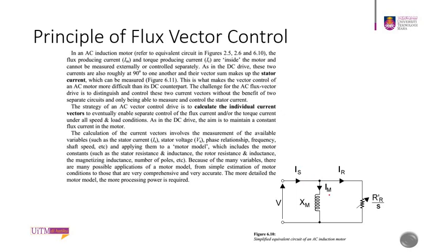Okay, and you can see here from the stator part of the motor, you can measure the voltage and the current input to it. And the rotor part, that is the rotor current, EMF, MMF, you cannot measure that. Okay, it's hard to measure. So with that, we can only control the voltage and the current of the stator part.